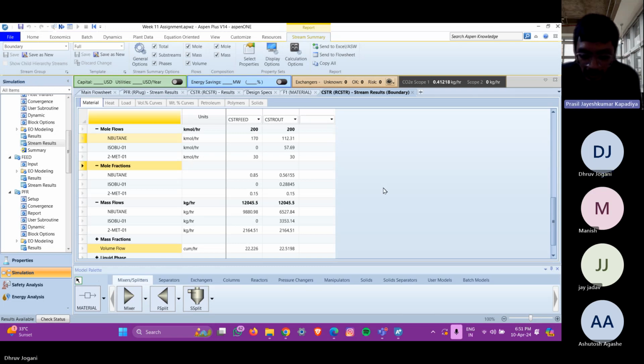Okay, now for the second case, it is for the CSTR. So your conversion is 0.7, right? So 0.3 will be Ca by Ca0. So 0.85 into 0.3. So your target should be 0.255 at the CSTR outlet. Just check it once. 1 minus 0.255 divided by 0.85.